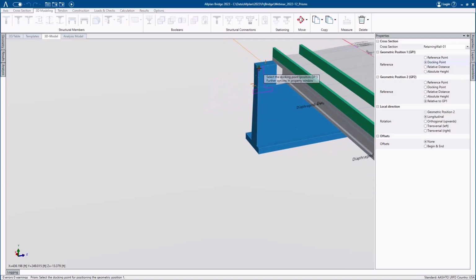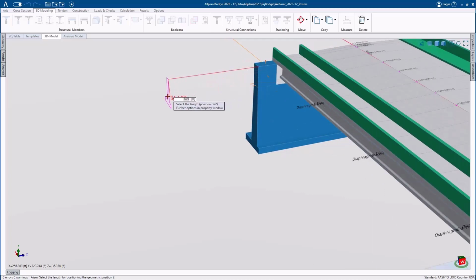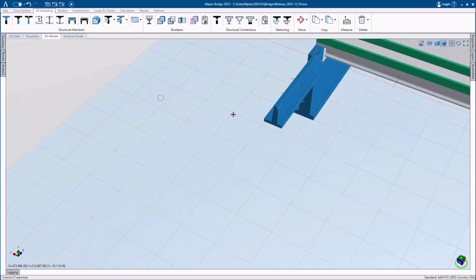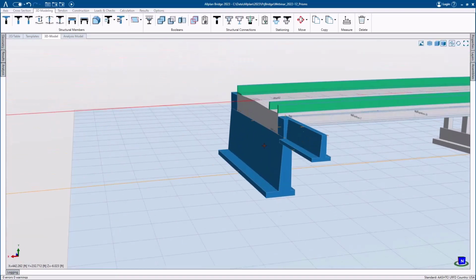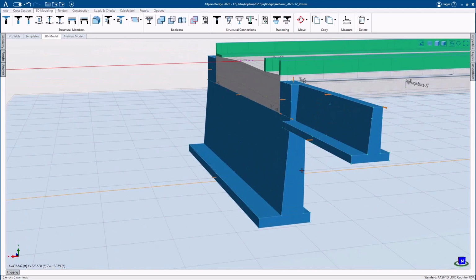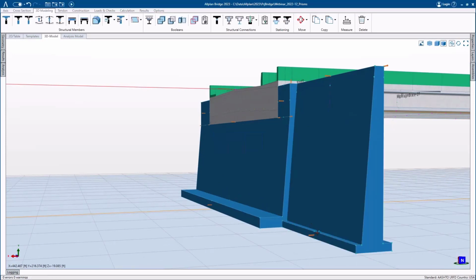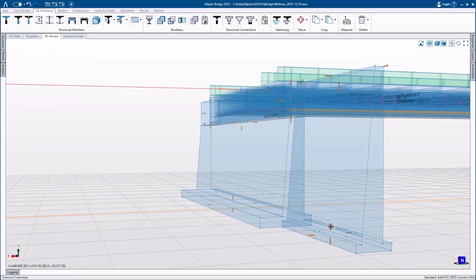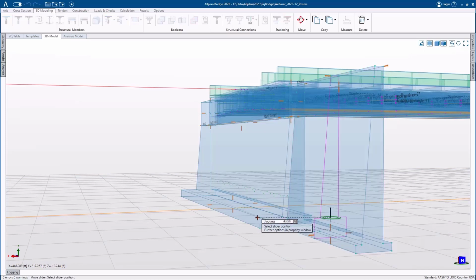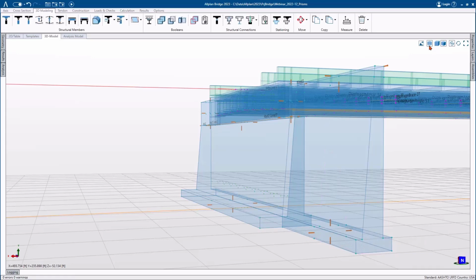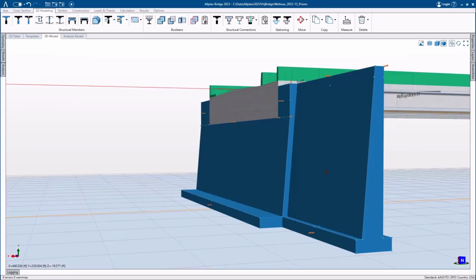Let's go ahead and select the corner here, and then we'll specify an overall length of this retaining wall to 35 feet. Cross section obviously doesn't have the correct dimensions within it for this particular location, but again, we can always adjust the sliders in order to match it up with some of the other geometry already within the project. So now I'm just matching it up with various docking points within the adjacent abutment body.